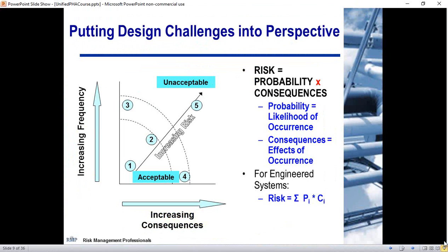So it's all about a scenario-based assessment when you're looking at things that can go wrong with a system. So the whole concept of likelihood and severity to get an appreciation for where you need to focus your design efforts is very important. This is the overall overarching technique of HAZOP, LOPA, and all the other techniques that are applied during the design process.